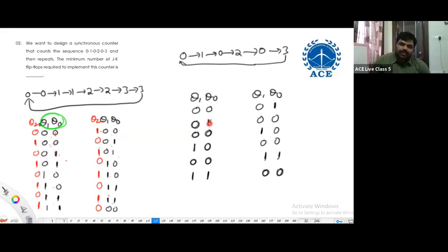But again, we are observing there is ambiguity. What is it? 0, 0 is having 0, 1. 0, 0 having 1, 0. 0, 0 having 1, 1. How many times is 0, 0 there? 3 times. Are they the same? No, they are not the same. When they are not the same, we have to differentiate. To differentiate three possibilities, how many extra bits? 2 bits. Already we are using 2 flip-flops, and 2 more bits are required. Then, how many flip-flops total? To differentiate the 0, 0s that occur 3 times, you need 2 extra bits. So 2 plus 2, it becomes 4 flip-flops.